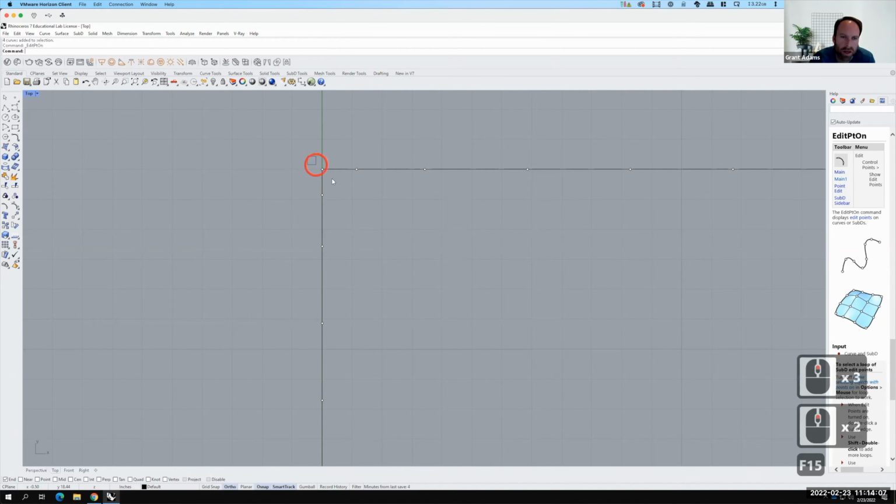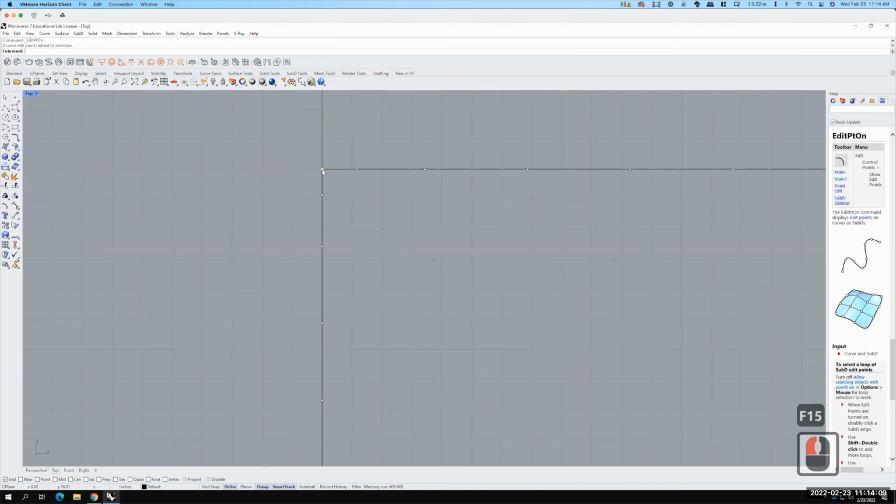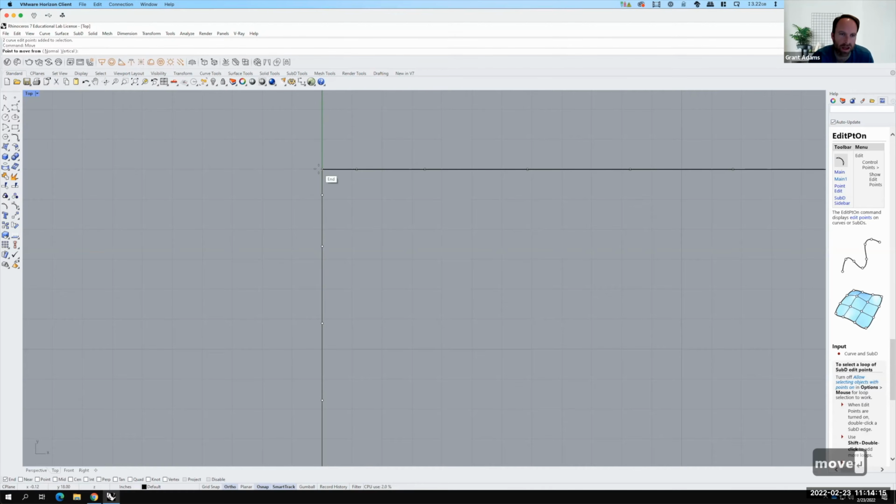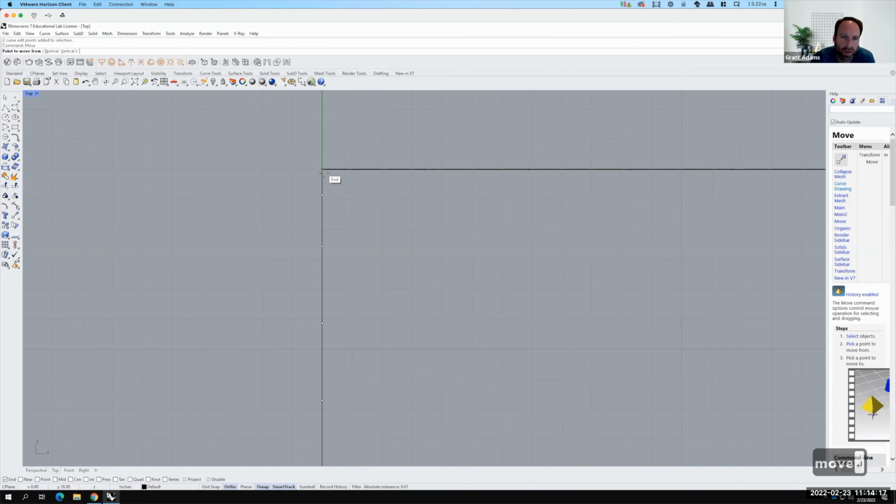Okay, so I'm going to select the corner point right here. And it's actually 2 corner points. It's one from each curve. And then I can actually move that control point. I'm typing move. Let me turn off my ortho here. And I can move that to kind of soften the corner. So I'm rounding over the corner like that. Notice that when I do that, it bulges out just a little bit as we create that corner. And that's more of what a real cushion does.